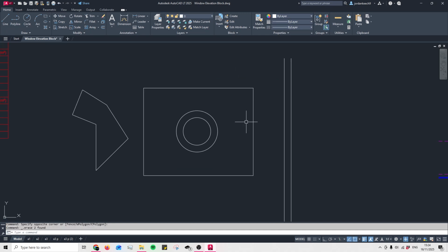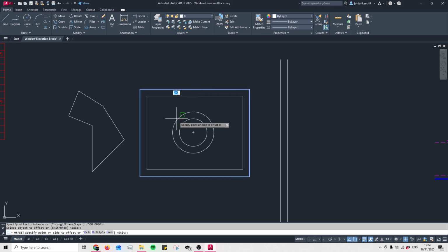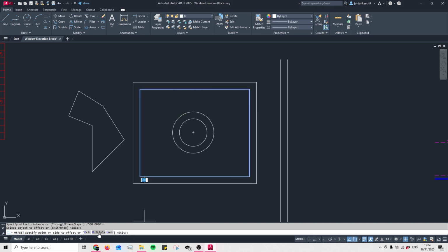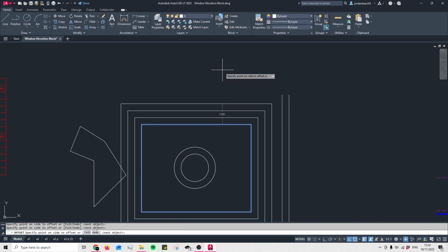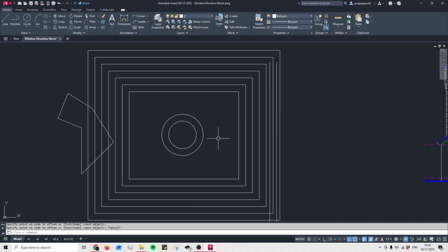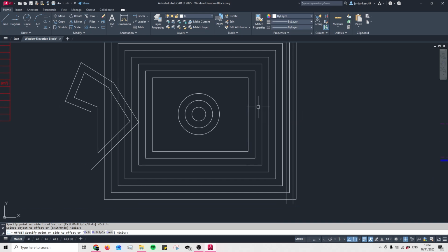And last but not least, if you're using a figure to offset, such as 500, once the geometry has been selected, you can then press on multiple at the bottom here or using M, and this will allow you to create multiple offsets by continuously clicking in one direction. And as you can see, the offset tool works on lines, circles, rectangles, and just about everything.